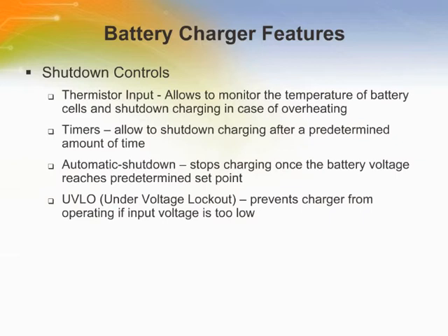An internal undervoltage lockout circuit monitors the input voltage and keeps the charger in shutdown mode until the input supply rises above the undervoltage lockout threshold. The thermal shutdown is a secondary safety feature in the event that there is a failure within the thermoregulation circuitry.